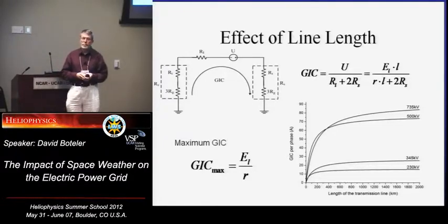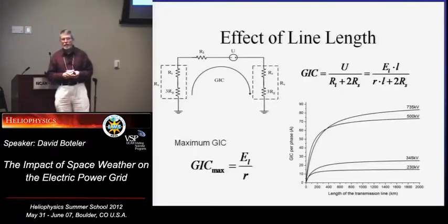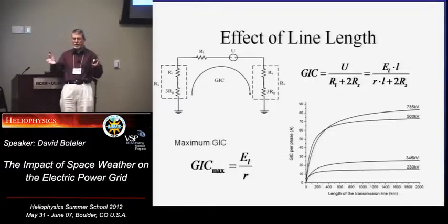You can reduce the arcing by having a much larger conductor, because then the radius of curvature is greater, and you've got less of the effect you get with a discharge from a point. If you can round it off, you get less discharge. But if you just made the conductors bigger, they'd be far too heavy. They found there's a trick they can do with that.